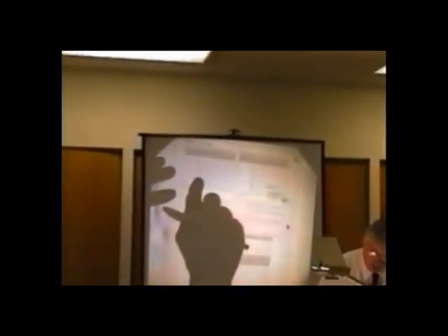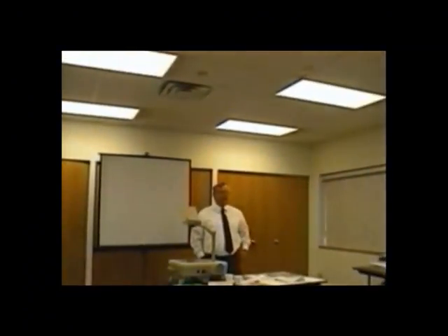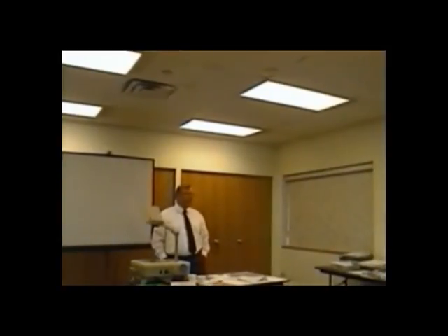Look at this though, huh? The only time we start, look at this, 3.5 ton is 5/16 too. 4 and 5 ton are 3/8. And now take a look at the 2.5 ton. Look at that. 2 sizes different, 1/4 inch. See? So, should we be installing 3 different sizes? Nah, it's too hard to keep carrying all the sizes. It's okay, all we got to do is add a little bit of refrigerant. That's all we're saying. That's only for the first 25 feet. Okay? And you can still use the same, and you got to follow the charts.